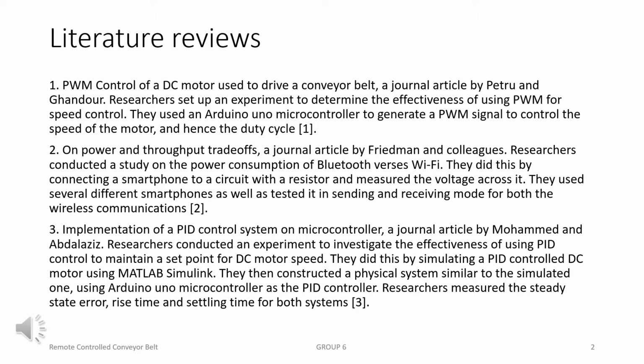Researchers set up an experiment to determine the effectiveness of using PWM for speed control. They used an Arduino Uno microcontroller to generate a PWM signal to control the speed of the motor, and hence the duty cycle. The speed of the motor and the corresponding duty cycle was measured in both directions. They concluded that the relationship between the motor speed and the duty cycle of the PWM signal was fairly linear, and hence using the PWM technique to control motor speed would be suitable.